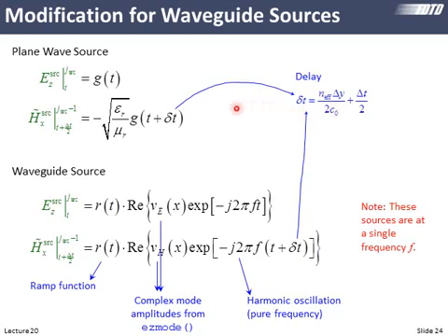Now for our waveguide source, here's what's going to happen. We have a ramp function that we'll talk about in a bit, but just pretend this isn't here right now. We just analyzed the slab waveguide through the cross-section FDTD grid, and we came out with our eigenvectors. So we look at the electric field component of the eigenvectors. For the fundamental source, this looks almost Gaussian, but we could have a second or third order. That's this amplitude function. That's what it looks like in the cross section.